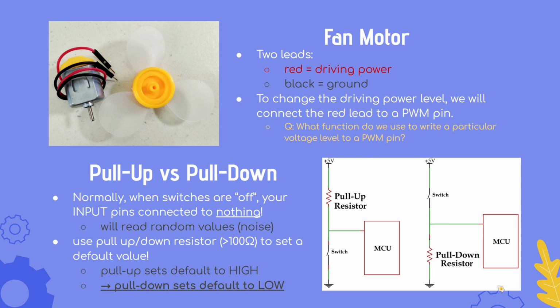Okay. If you try that on a regular digital pin that's not PWM capable, it's probably going to switch. It's only going to alternate between 0 and 1 in the first place, but I don't really know the threshold for that. In some processors, it's like 33% of what you put in is going to draw a 1, everything else is 0. It might be 50-50. I can't say that. Basically though, just use the PWM for the PWM, okay?